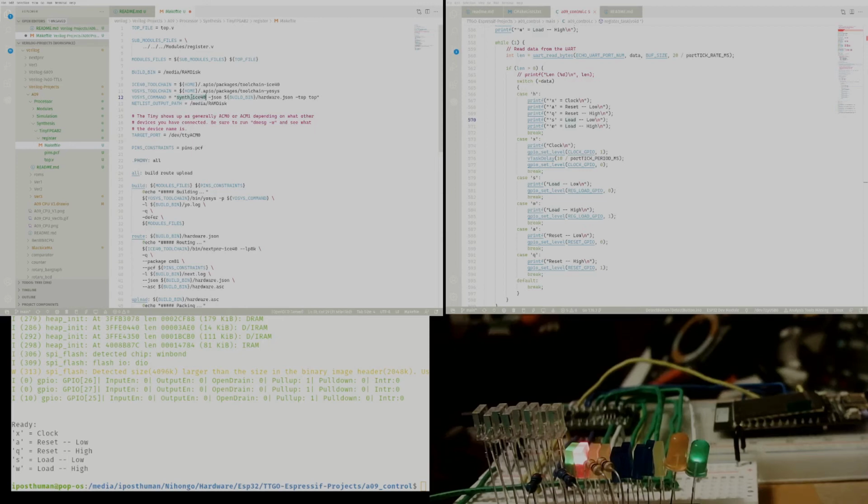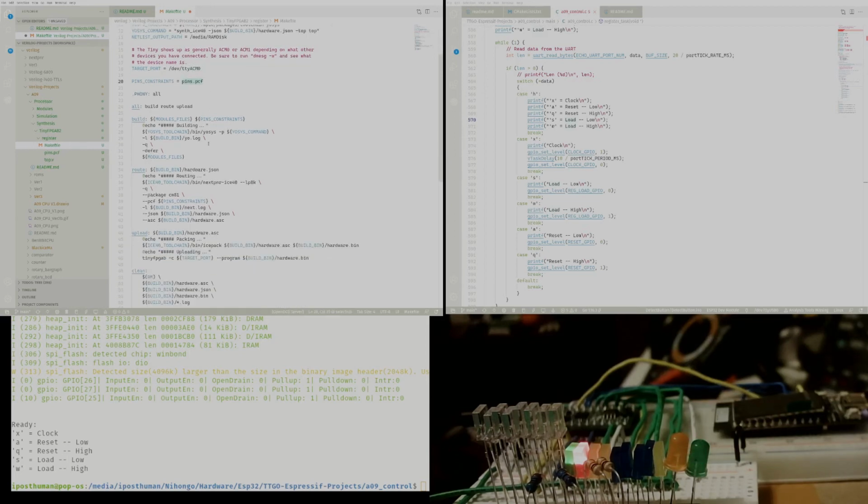And this is specifying an internal script, and we could take a look at it. It's just a text file that lists a lot of steps that Yosys will go through in reducing logic in your circuits. And that's what this script is actually doing here. Of course, we really need to define the actual device where it's located. For the Tiny, it appears here. We also supply the pin constraint file to the builder.